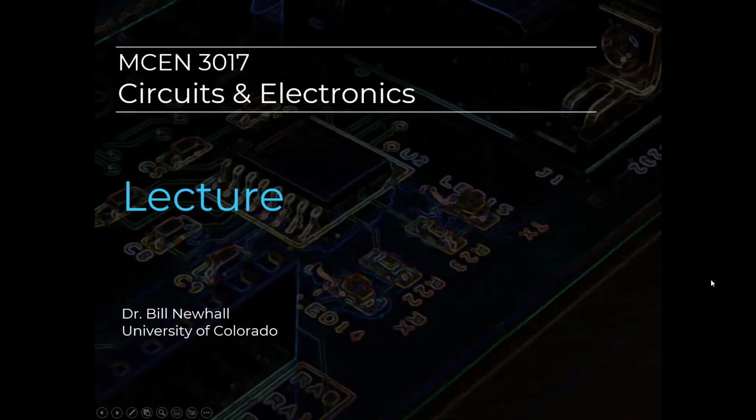So I wanted to continue just a little bit with the Thévenin equivalent circuit topic. Last time we talked about Thévenin equivalence, how to calculate the Thévenin equivalent circuit, and then maximum power transfer, right? If you want to maximize power transferred from a realistic source to a load, you make that load's resistance equal the Thévenin resistance of the source.